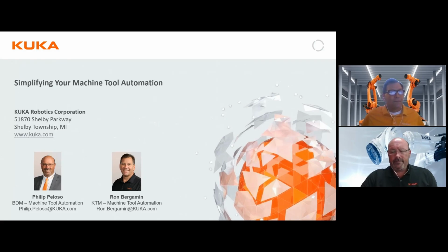Okay. We have someone asking, FANUC controls are out in controlling a KUKA robot, correct? Yeah, it's almost a trick question, I guess. We can certainly interface to FANUC controls through some of the simple interfaces like a field bus or digital I/O, but we don't have the same control capability for MX Automation. They actually have a closed system where they have something similar to MX Automation, but it's proprietary for FANUC robots only.